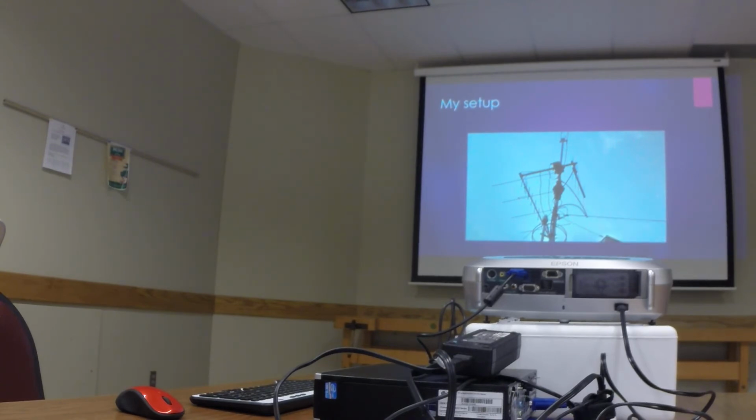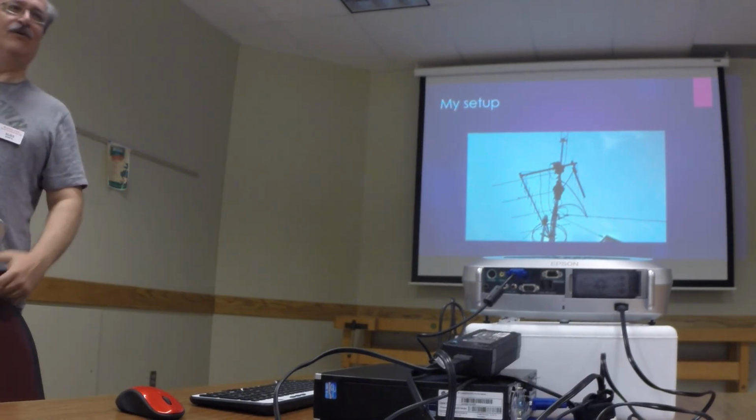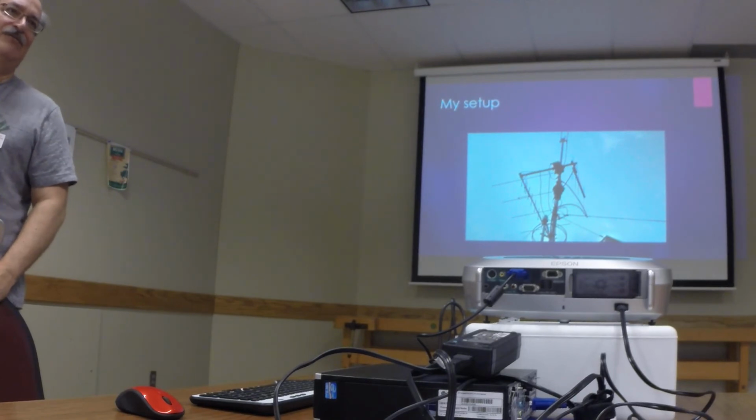And VHF, not too sure. But yeah, on the receive side, your receiver and antenna on the ground are a very integral part of making this work. Absolutely, because they're working off of solar cells and a small battery. The CubeSats especially have the solar cells on the outside of the cube, and sometimes one antenna for just UHF or a pair of antennas, and they're just little whips, is all they are. They can't have anything too fancy, because every tenth of an ounce or micro ounce counts in a payload. So they're very fussy about how heavy those things are.